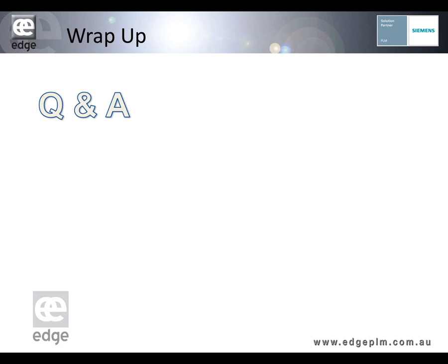Okay, we're coming to the end here. We've got a Q&A session now. I see there is a question here: how do you create the solid from the stitched feature? In ordered, it'll do that automatically. If the stitched feature is manifold, in other words, all the faces form a closed box, if you like, it will give you a prompt saying, do you want to make it a solid?